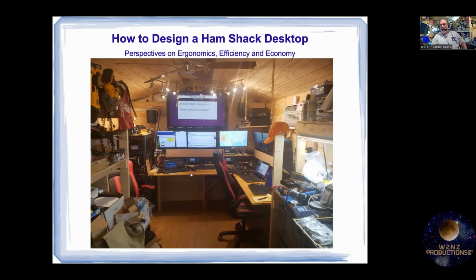It also has the effect of keeping the shelf, which is a 2x12, from sagging, because think about it. If I have a horizontal bar, a beam, and I put something perpendicular to it to stiffen it, it'll keep it from sagging. So it's like a piece of L stock, not an I-beam, but an L stock. So it's got a little more structural strength.